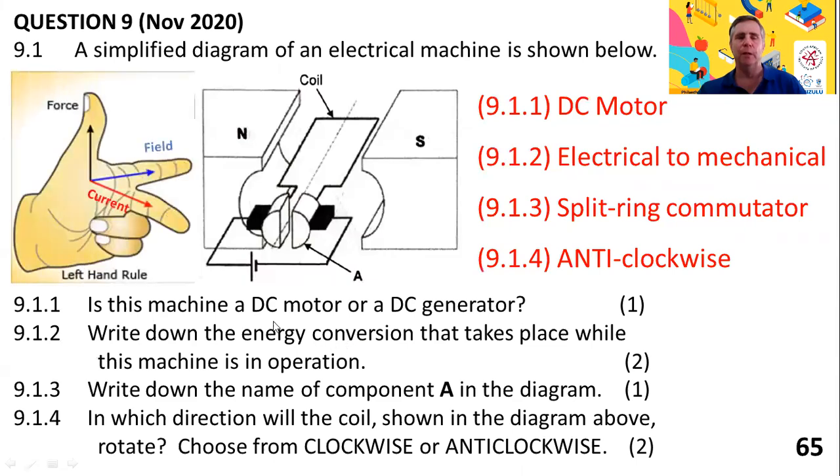Let's do that carefully. First of all, we're going to use Fleming's left-hand rule for motors, and we're going to notice that the field goes from north to south. The current, because it's conventional current, goes from positive through to negative. Remember, conventional current is effectively flow of positive charge. And because of that, we can put those together, and we see that the thrust or the movement will be down. Now, you'll have to do this for yourself, but you have to take your left hand and essentially turn it around backwards like that to show the downward movement. And it's not going to look the same on the video. You need to try it for yourself. So that wire will move downwards, which tells you that the whole coil will move anti-clockwise.